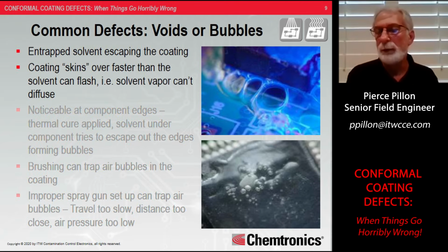You may have a bubble. Is it a defect? Well, it depends. If it does not fit that criteria, if it's not bridging lands, adjacent components, whatever criteria you have set up, then it's a process indicator. Something has gone wrong in your actual application of that process, and it should be addressed and it should be resolved, but it's not a defect.